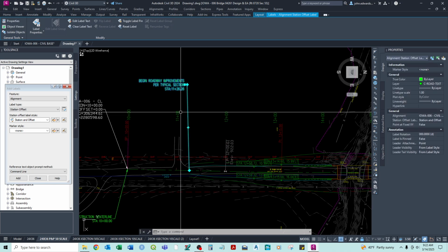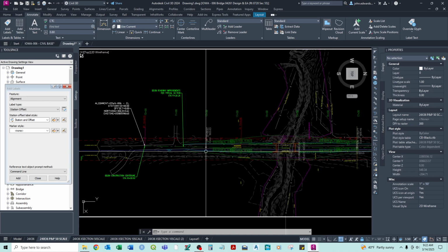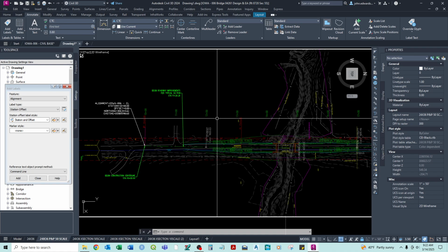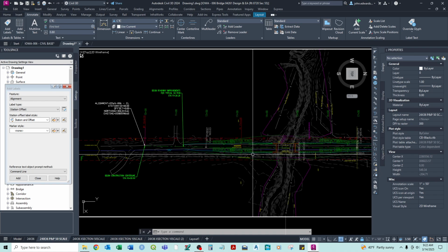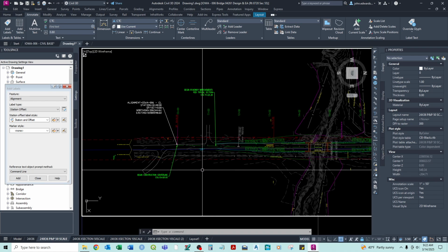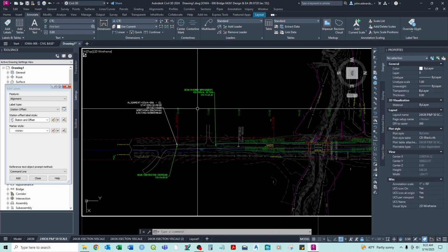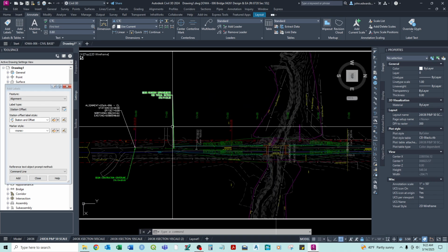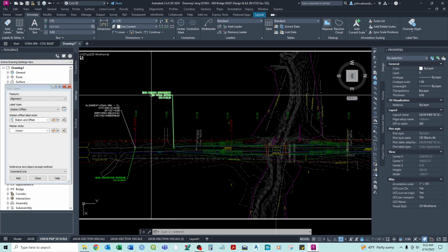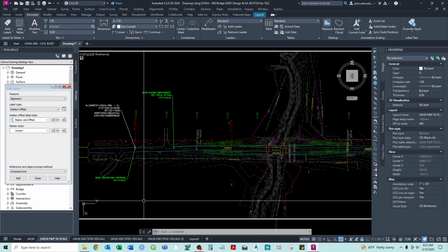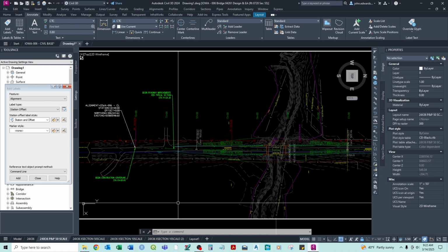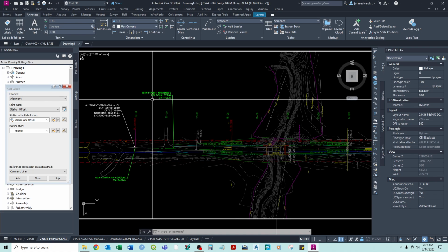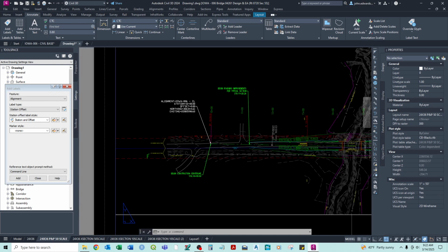Okay. And the one nice thing about when you label within your layout view, within your profile view, you can see how things look exactly and how it will look. You can see how your station labels, because you'll want to avoid those when you're doing your other labeling. And so this can get quite complex and convoluted in here, where you have to try to avoid a lot of features to draw all your lines, but it's a whole lot easier to see here.